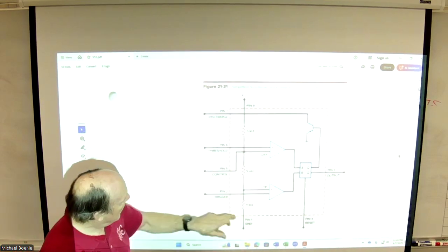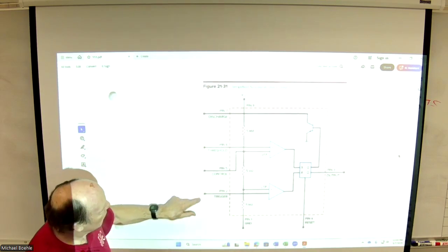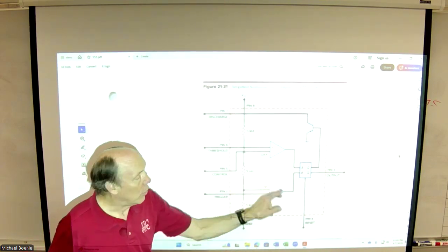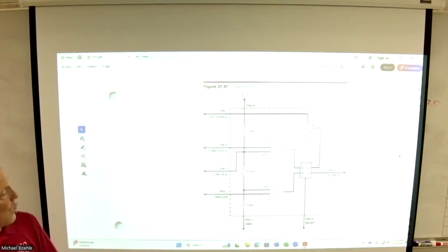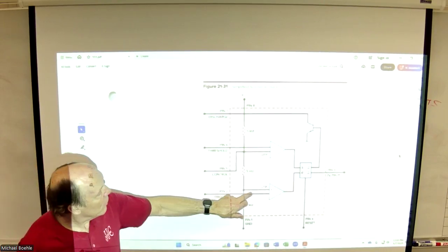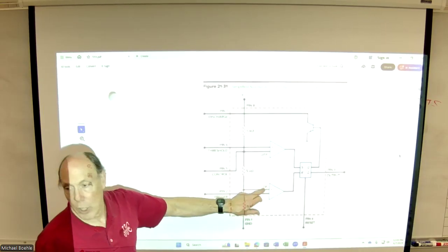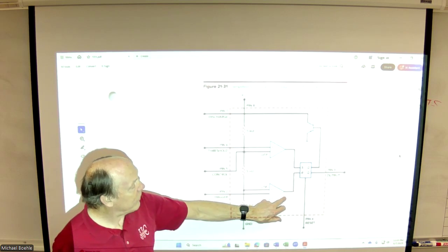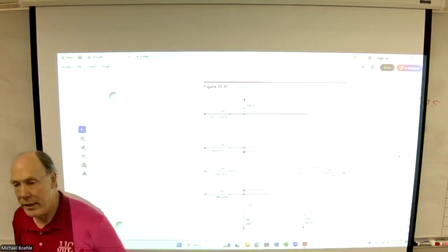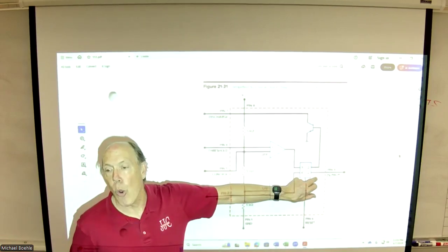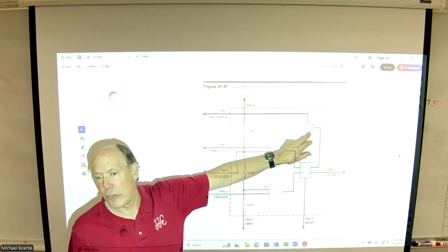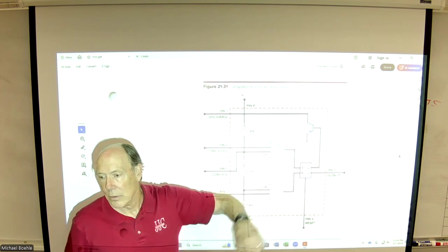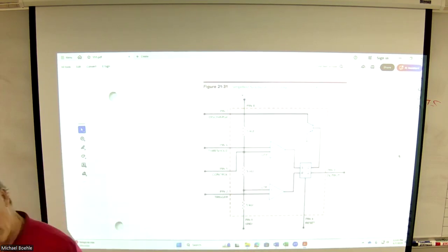Now, when my trigger, which is the other input to the lower trip point comparator, drops below the lower trip point, that activates this comparator, which activates the reset input, which makes Q go low. So when Q goes low, what happens to this transistor? If I put 0 volts into the base of the transistor, that transistor will be off.